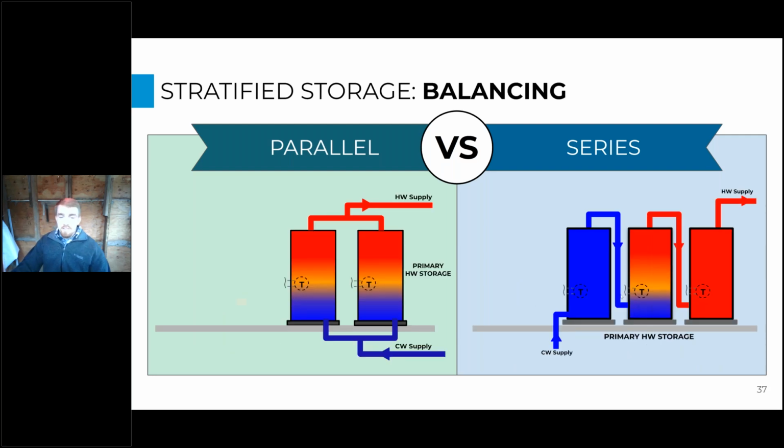And so right now, parallel tanks look a lot more promising than tanks plumbed in series, and they're a lot more common in gas systems too. But the reason that we plumb these tanks in series so often in a lot of applications is because it makes for a lot better balancing of flows, right? If you're dealing with a parallel tank setup, you could have, say, 2 to 5 storage tanks here, and if the pressure drop through any of these tanks is inconsistent with the rest, then the flow entering and leaving that tank will be inconsistent with the flow through the rest of the tanks. And we've talked about the importance of stratification and using that stratification layer to gauge when to turn that heat pump on.